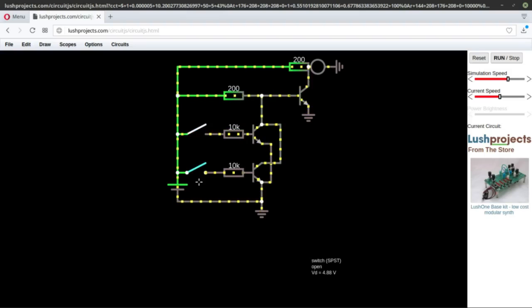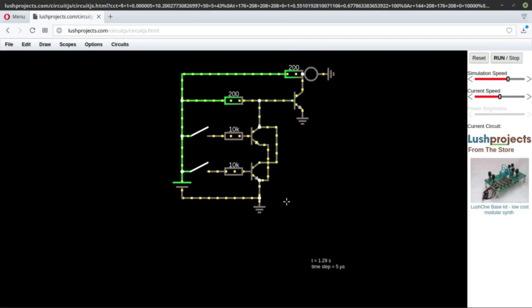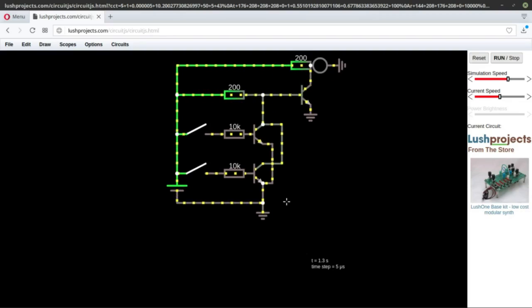When either of them is on, this is pretty much an OR gate. Only when both of them are off does this light turn off. So we have the OR output right here. We have learned NOR and OR gates so far.